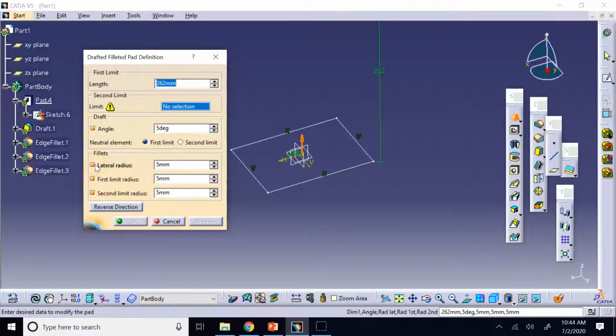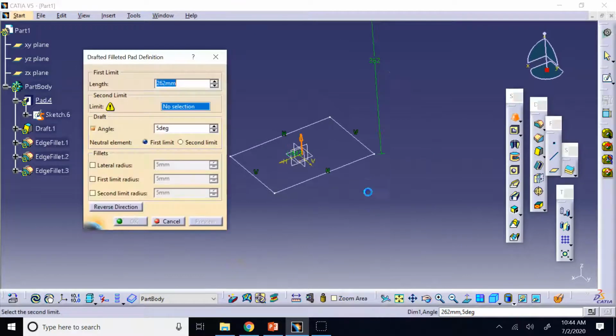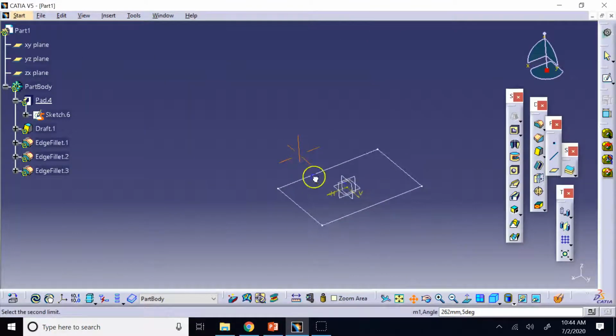And it can also fillet the edges of that prism for you. Now, if you don't want the edges of that prism to be filleted, turn these guys off. So it only gives it the draft, no fillet. And I'll show you what it would do, but you don't get rounded edges, you would get sharp, straight edges.